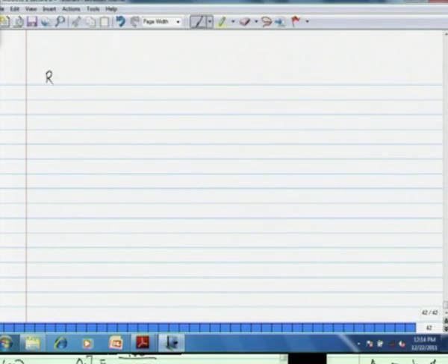Now the next question is about determination of the reactor heat load. Now reactor heat load is essentially for reactor 1. For the second reactor, reaction occurs only at 80 degrees centigrade and the reaction is rather fast due to the unstable nature of ketene, and therefore there is not much heat load there.